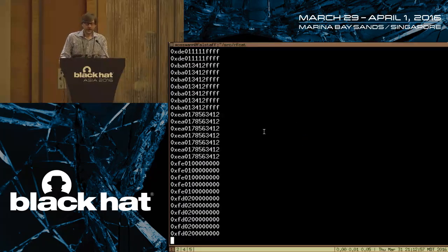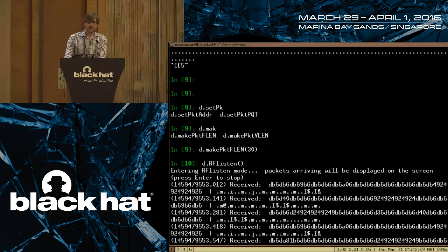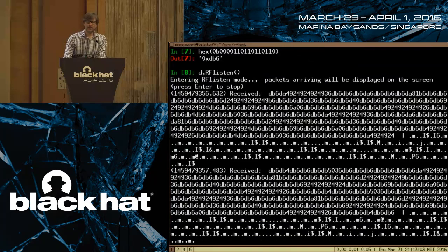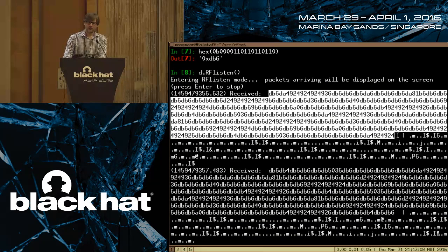Basically, the way I would do it, if I go back to my window here and scroll back up to where I was looking at the very first things I was capturing, where I've got a long string that contained approximately three packets of raw symbol data before I was decoding it, the easiest thing to do is just tell RFCAT to transmit that. I can just copy and paste that, tell it to transmit, and do a replay attack.